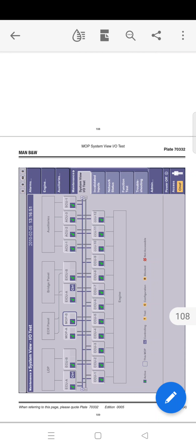Now these are the inputs. What are the inputs given? 4 to 20 milliamps coming from the transducers, plus minus 10 volt input voltage signals, and also switches and 24 volt binary signals. Outputs we have again 4 to 20 milliamp signal, plus minus 10 volt signals, contacts and high speed semiconductor switches for activation of the exhaust valve of the ME engine, for instance. Duplicated control network for security, serial communication controller for either a remote input output network or point to point serial communication, and a service channel to be connected to a laptop PC for service purposes.